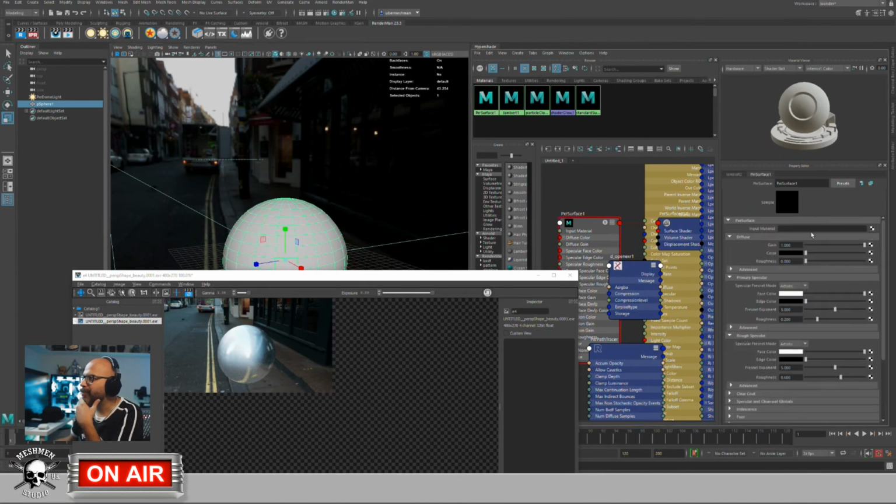Let's take a look at my Pixar surface again. So here the diffuse color is set to 0, and I have my artistic specular here. If I set this to 100%, then it's going to be like a mirror. If I set the roughness down to 0, we can see now it's reflecting. This is correct for a metal, but if I would have my color also set to white, this is not really a plausible way to render something. This is essentially I've broken it, because if this would be a mirror, you can't have diffuse, at least in Renderman.